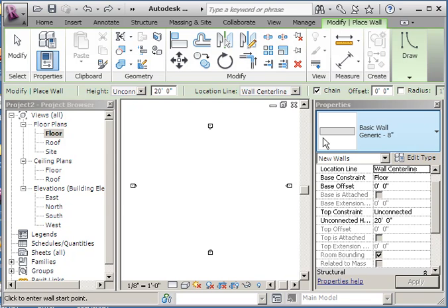And now it says once it is in the drawing area, the cursor will change from an arrow to a plus sign. This indicates that the program is ready to input. Now in our activity, our activity is to complete a shed, but it's also to follow the directions so that we learn how to make walls and other items in multiple ways. So our next step is called method 1, individual walls. So how do we make individual walls?